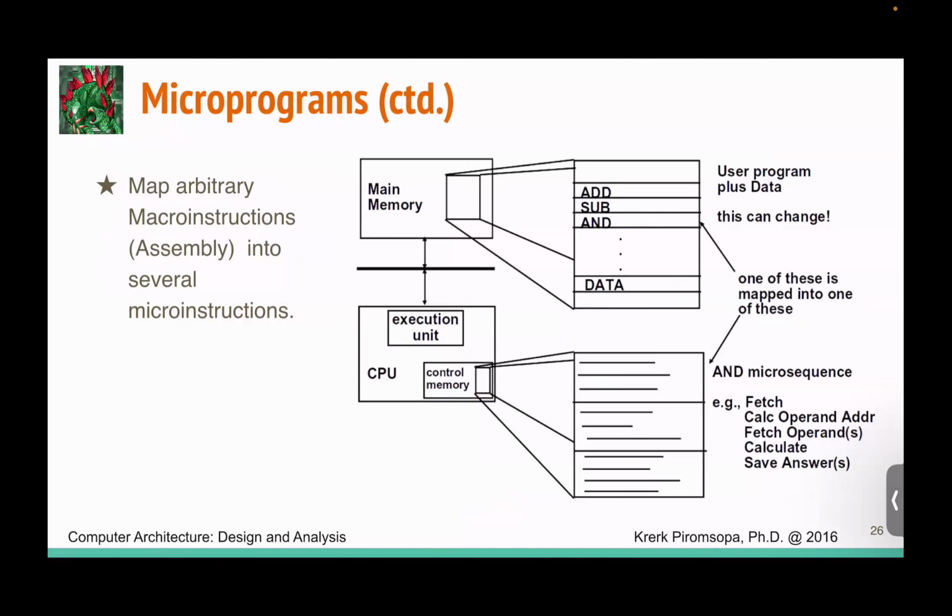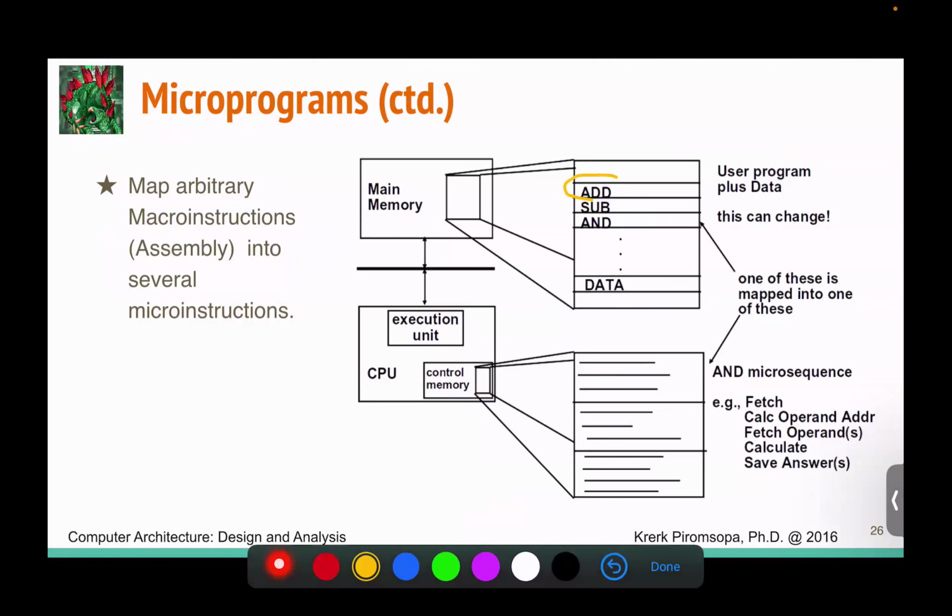So it's like this. When you have an instruction outside, you fetch it in, it's gonna convert into a bunch of small micro sequences, basically one sequence for one clock cycle, like that. So sometimes people call this ISA, they call it macro instructions, and they call this sequence micro instruction, just the word anyway.